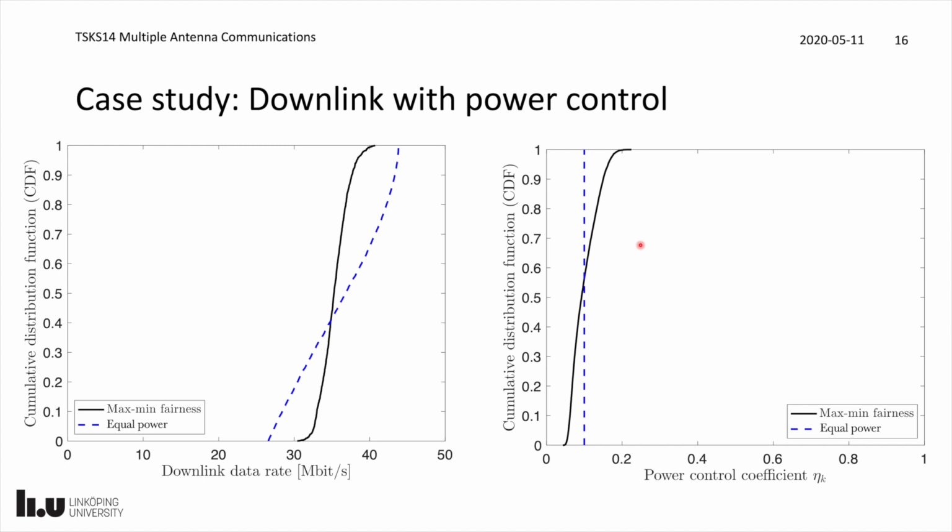Well, in the uplink, since the signals are going through your own channels while interference from the other users are going through other channels, we see these large differences: if someone has a better channel than you, they need to cut down on the power to not interfere with you too much. Because if you have a 50 decibel difference in your beta, then that means that the users that have a much better channel than you will have to cut down on the power by roughly 50 decibels in order to deliver the same received signal quality and therefore a similar amount of interference.